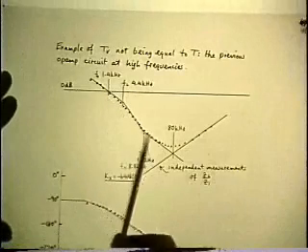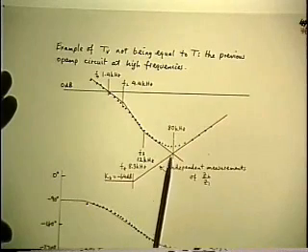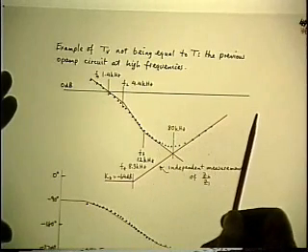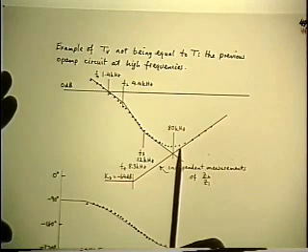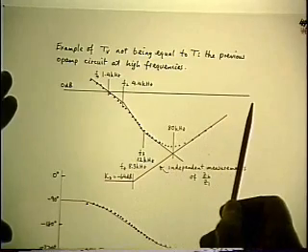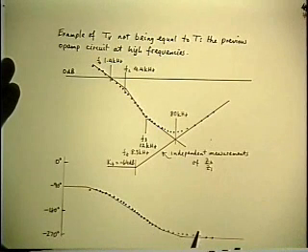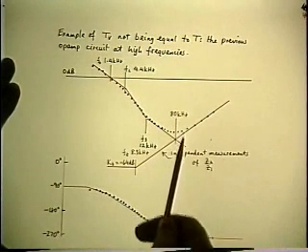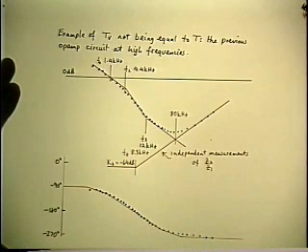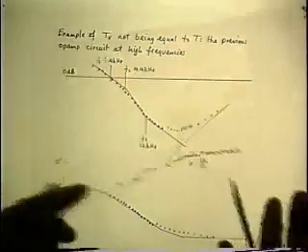Because it explains why the measurement of T sub v started to deviate from T at 81 kilohertz, and it turned around according to a double real 0 at the same frequency. So at that frequency, the -1 slope was changed to a +1 slope. But it also explains why there was no change in the phase, because the only difference is a right and left half plane 0 at the same frequency, and the phase contributions cancel. One's a lead and one's a lag at the same frequency. So that is now a full interpretation of the measurements.